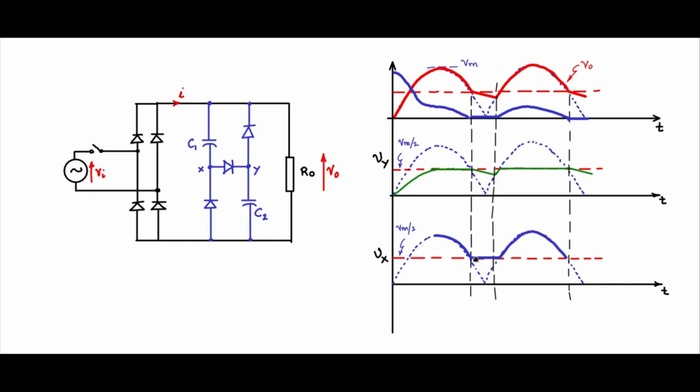And this point will be the 0 point because it is during this time this diode is conducting. When the capacitor is discharging during this time, the diode is conducting, and then you will have a horizontal. So this is the type of waveform that you will see for Vx and also across these diodes.